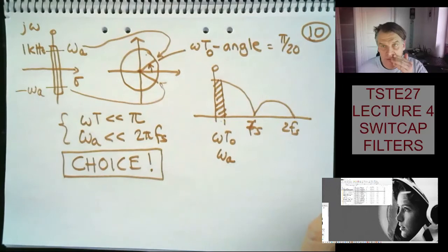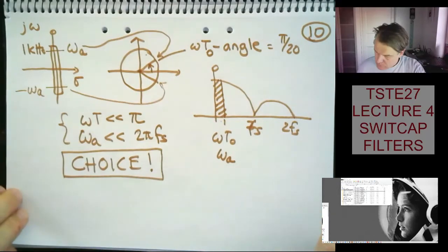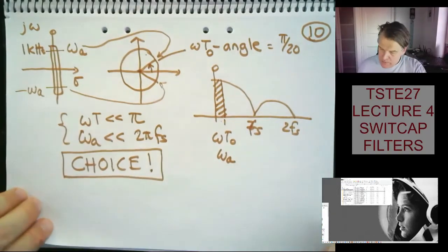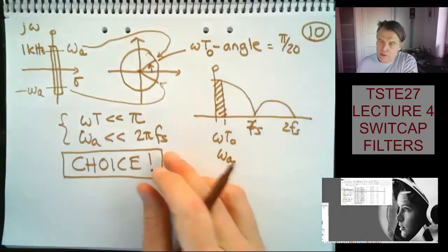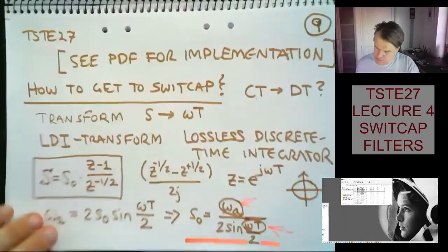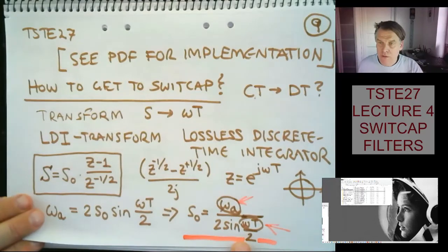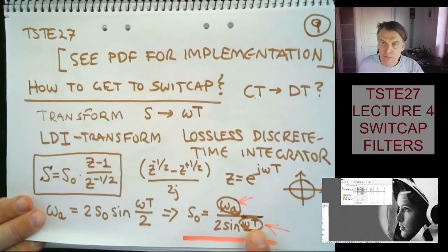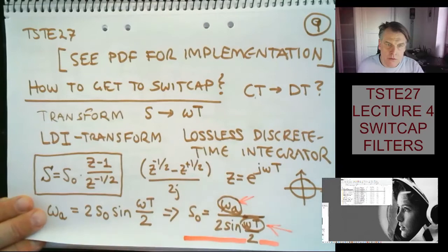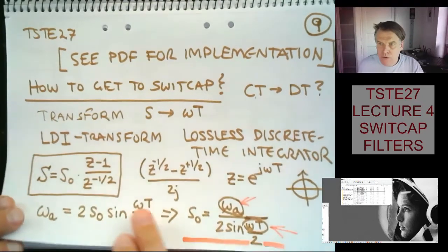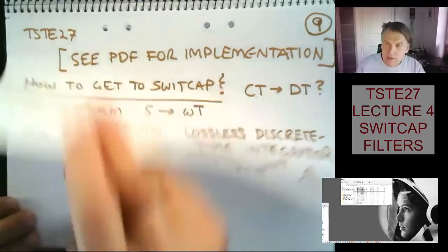That particular scaling factor. All right, and you see it's not linear. It's a sort of strange equation here. So for example, if you choose to double your sample frequency, and if you maintain the S naught, that will have some nonlinear impact of what that frequency corresponds to in the continuous time domain. So beware here a bit of your choice and how you implement that.